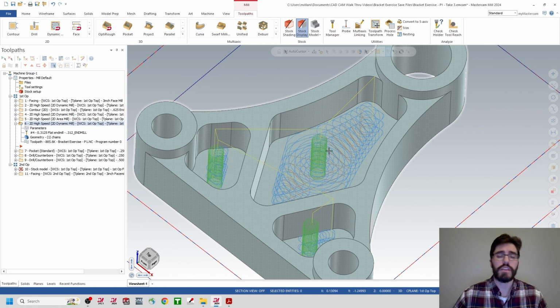So with this pocket here, you could leave it as big as you want, and these two smaller pockets, you could separate those and you could have a smaller entry motion for that helix radius. However, I'm just going to leave it at that 62 thousandths. You can actually update it if you want to, but we're just going to go ahead and move on into our seventh toolpath, which is going to be the finishing operation for all three of these pockets.